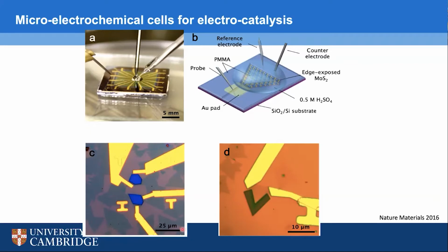So in this image here, you might be able to make out these dark triangles in the background. And what these dark triangles are, are CVD grown MoS2, they're monolayers. And on these CVD grown MoS2, we've patterned these electrodes using standard lithography. But the way we've made this device is that the only part that is exposed here is this blue region. The gold electrodes and everything else is covered by an insulator. Of course, the gold electrodes are contacted to MoS2, but the only thing that is exposed here is this blue region of the MoS2.